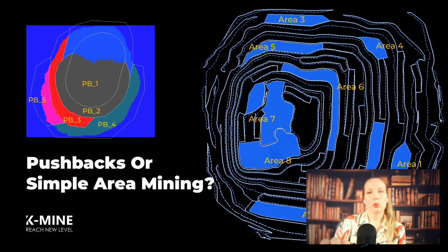So if you're wondering why and what's the difference, we've been doing this for ages, it's been working fine. Let's compare how different mining methods impact operations, intensity, and other factors. First, let's clarify what we mean by conventional mining. This involves progressive pit development where there isn't a clear mining front, but rather multiple mining zones influenced by specific mining conditions. Sometimes there might be a direction to the mining operations, but it wouldn't qualify as pushback due to the mining approach. With pushbacks, a cut is made to a specific width from the pit top and is mined progressively downward until reaching the maximum feasible depth.